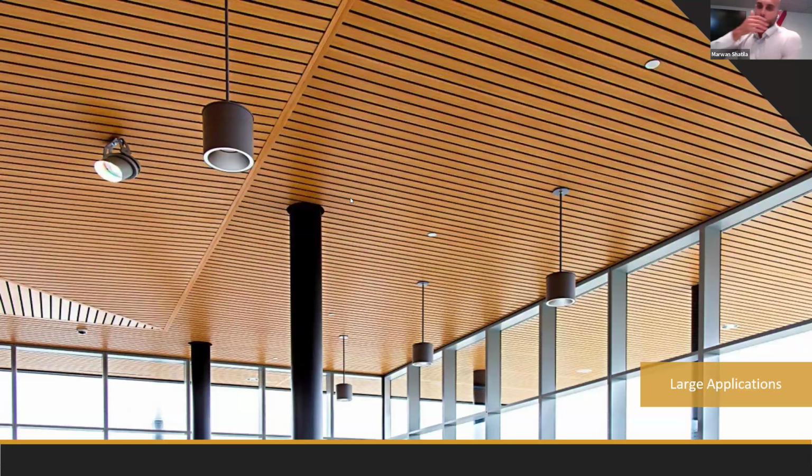In the photo that you all see in this application, you'll actually notice that there's an expansion joint running in a few different directions. And the reason why is because that expansion joint will also allow a pivot in the direction of the panels. So it's very clear to see towards the bottom left-hand side where some of the panels are running vertically, whereas some of the other ones are running horizontally.